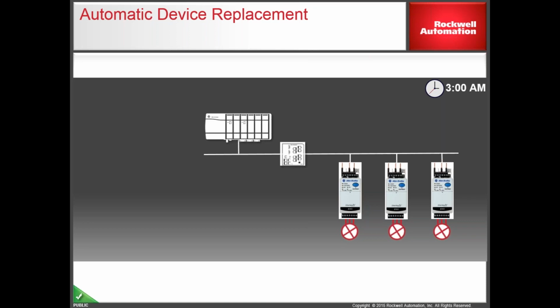Yeah, that's what we did. We inhibited that one, created a new _1, and re-upped. That's really the best way to do it, before you apply it, before you dump it into the I/O tree and make that change permanent. You have to go in there. So now we've got a couple of underscore modules we have to clean up.